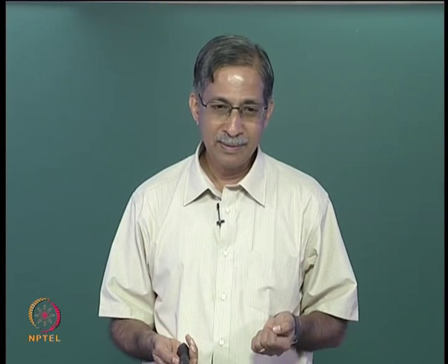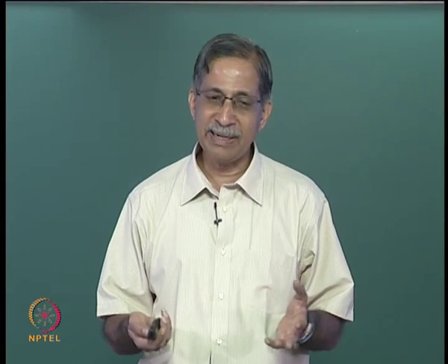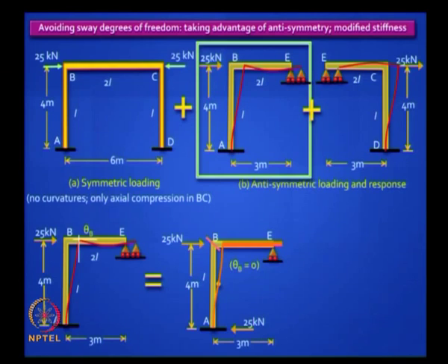Will the moments be clockwise or anti-clockwise? Well, there are many ways of figuring it out. You can look at the figure and decide. It will be anti-clockwise. Another thumb rule you can take is, whenever I have a clockwise chord rotation, I will end up with anti-clockwise end moments. Okay, we proved this earlier.